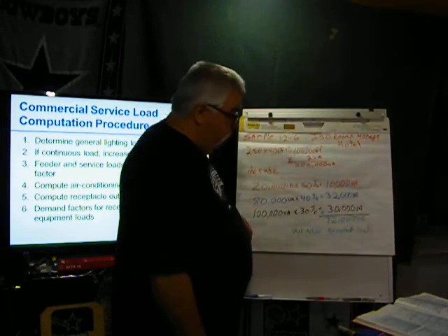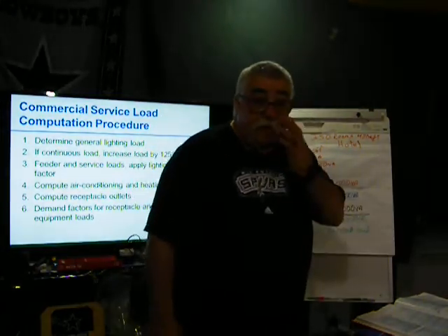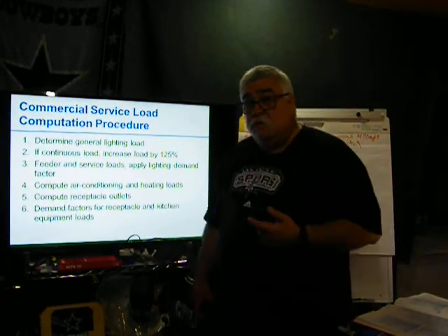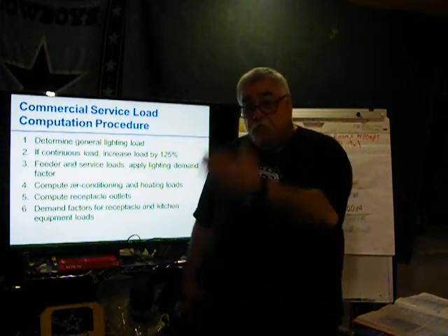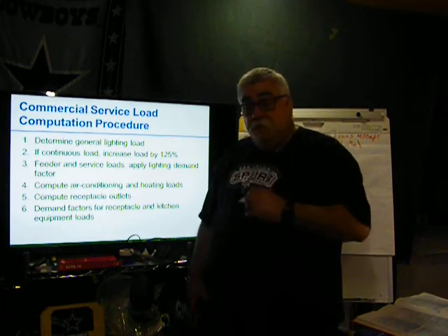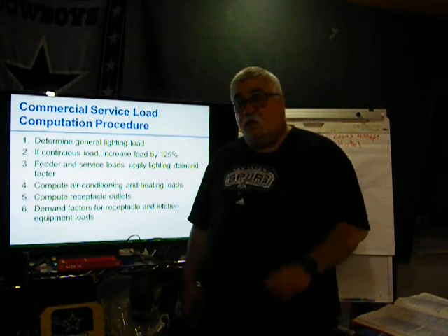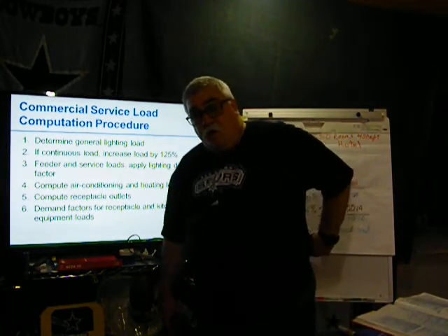We're going to put all that together. So next, now that you got your lighting loads, you got all your general lighting loads, divide that by your applied voltage, and that gives you your amperage, and again give me a wire size.